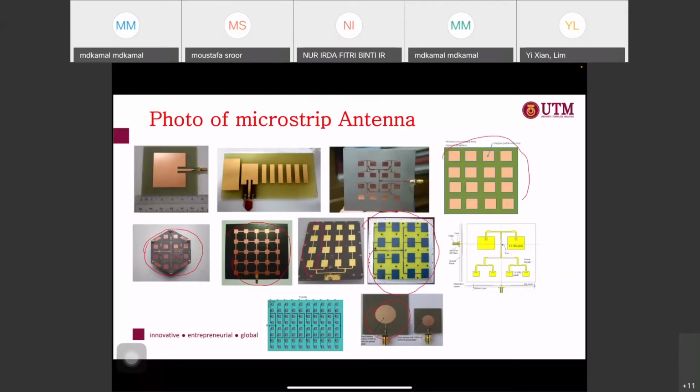So this is just a planar microstrip antenna because you have the directions of Y and X here. Okay, so you have both Y and X, so this is called planar. If you only have one direction like this, you can see that this is linear. We also can have a structure like this, arranged in terms of a circular. So this is the circular here. Okay, this is just an example.